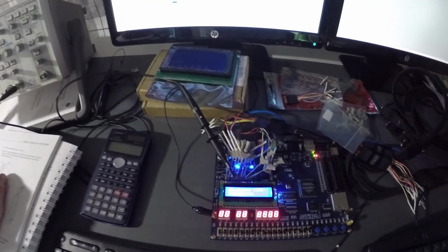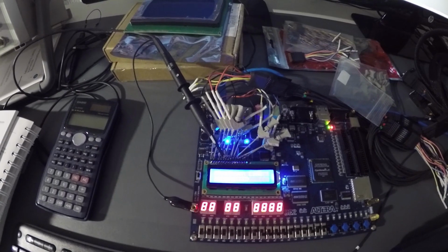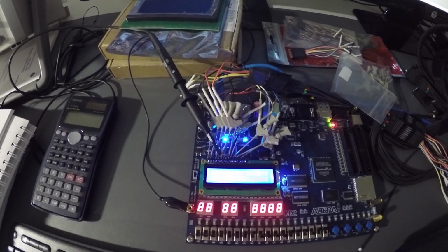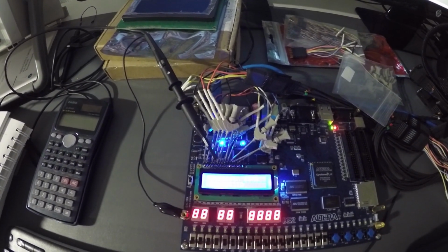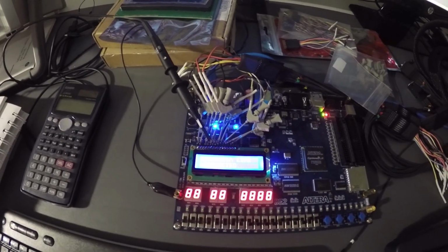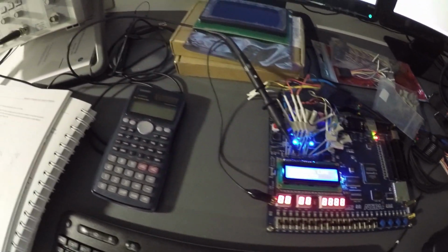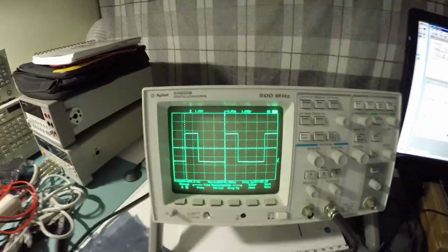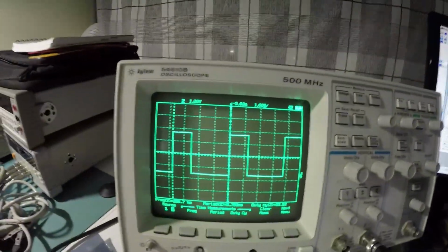So let's move on, and I'm going to start to use the actual new code that I've posted on the web page. We'll compile that with Quartus, and then we'll be able to see the actual intended frequencies that we declare, and it should show up correctly here on the oscilloscope for that LCD enable line.